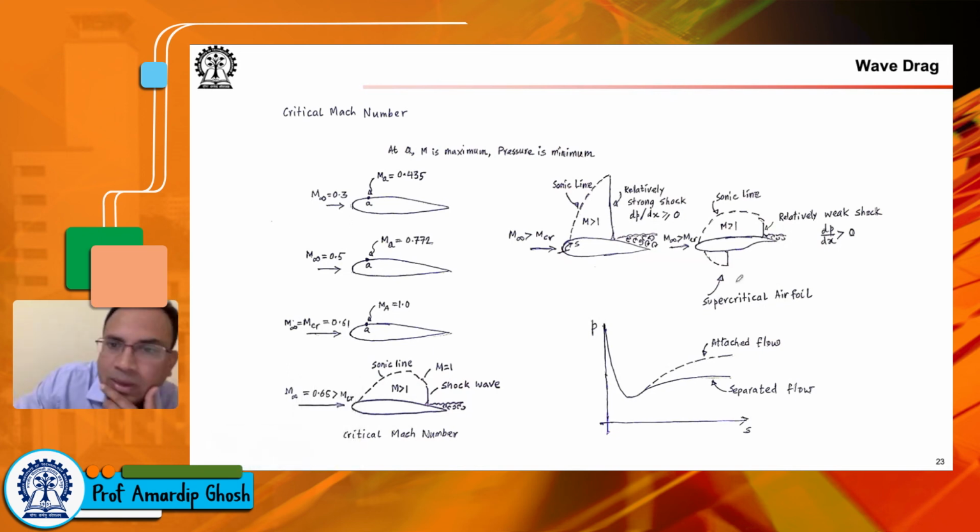But here, what happens is, while the top surface is flat, like in a thin airfoil, the bottom surface is thick enough, and it has this very large positive camber at the trailing 30% region. Okay, if you think of the full chord as 100%, then in the initial portion of this region, you actually have negative camber for the supercritical airfoils.